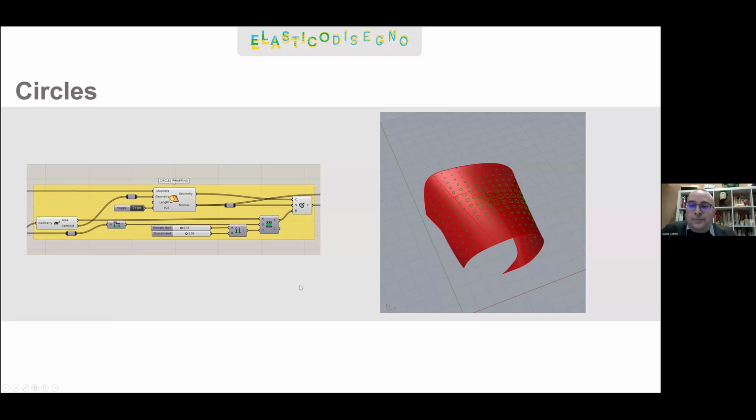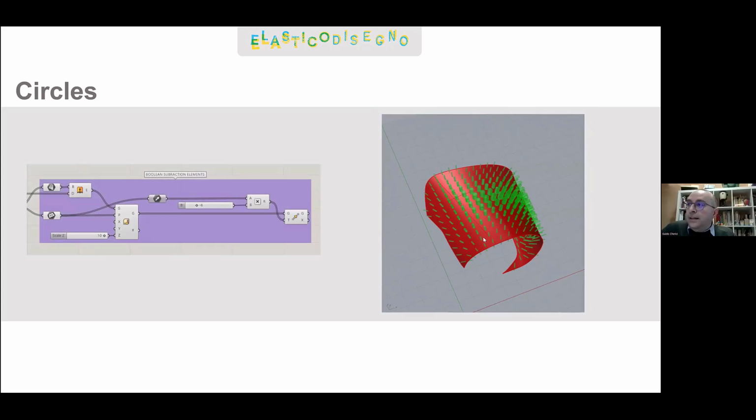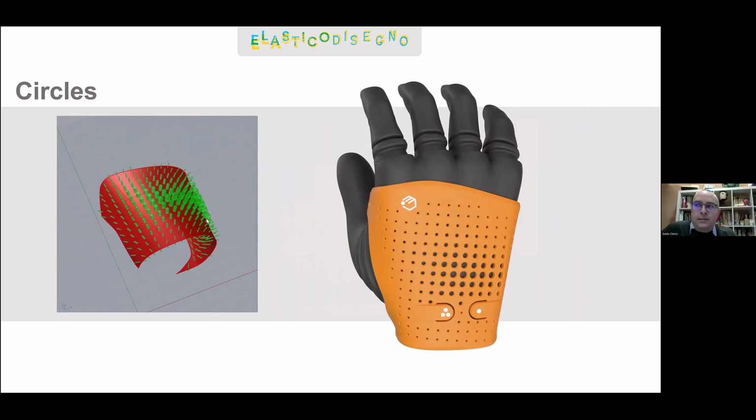And so we used Grasshopper again to extract the center of the circles, together with their normals, and then project them onto the surface, obtaining this way this series of cylinders, which we then scaled along the z-axis to make sure that they went all the way through the cover, creating what we call the porcupine, which was then brought back into Creo to punch holes into the actual covers.